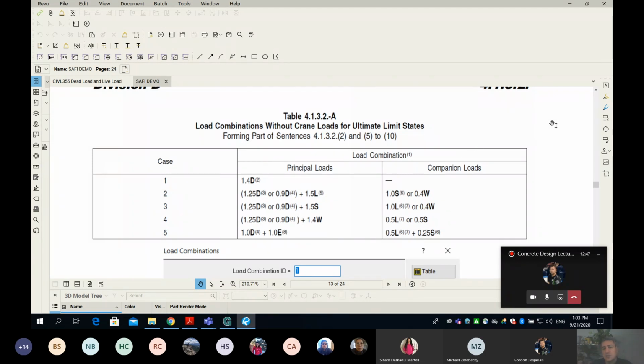The idea here is very simple. When loads act on the structure, they don't act individually. They act together on the structure, except for the dead load, because simply the dead load exists and doesn't go anywhere. However, live load can come and go. Wind load same, snow load same, earthquake is the same. Now you can see we don't have one load combination. We have so many of them. Even if we take one of them, it will generate for us sub-load combinations.